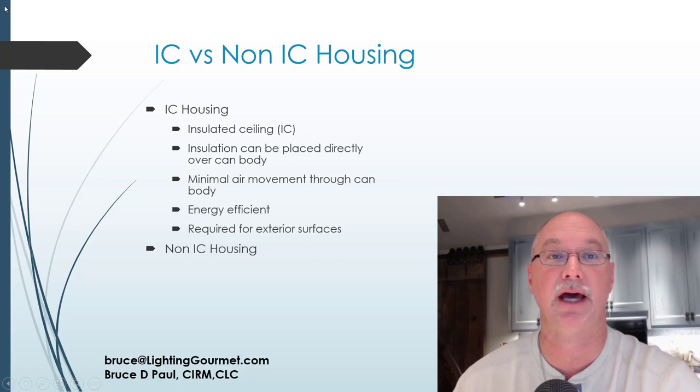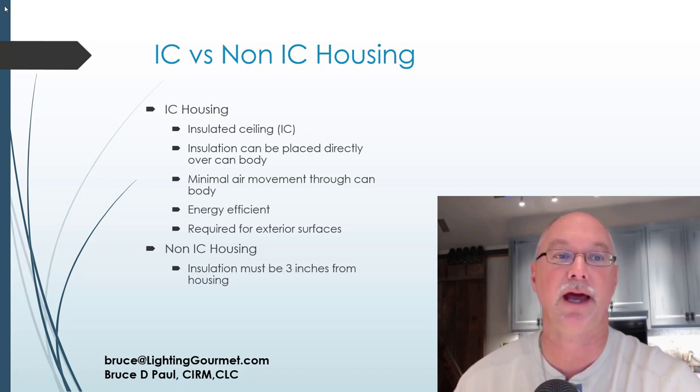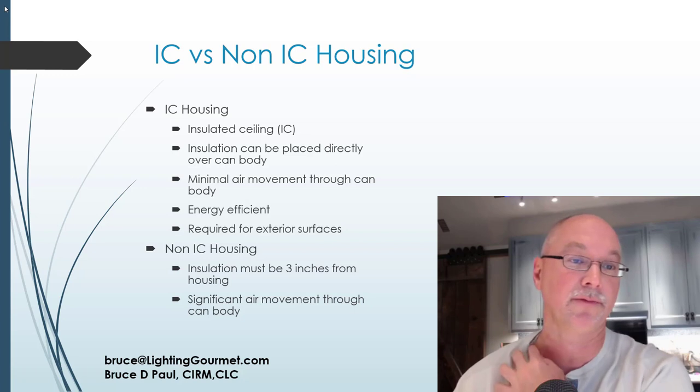Non-IC housings are just that. They are meant to not have insulation on top of them directly. It needs to be kept 3 inches or more away from them. It's a pretty easy thing to understand. It's not so easy for it always to happen. If you have a can that shuts off and then turns back on the next day or later on, you most likely have either lamped it with too high a wattage light bulb, or it's covered in insulation and it's non-IC and it's overheating, and so, for safety reasons, it automatically shuts off.